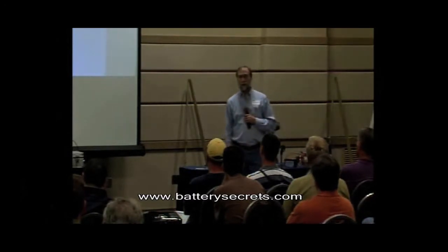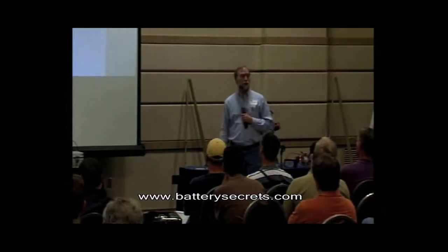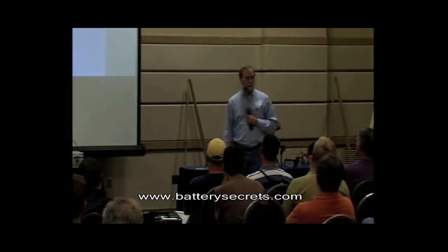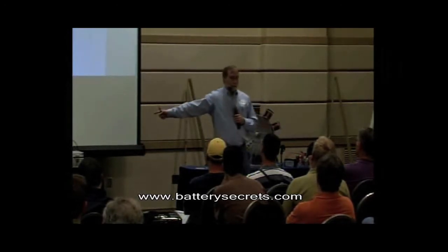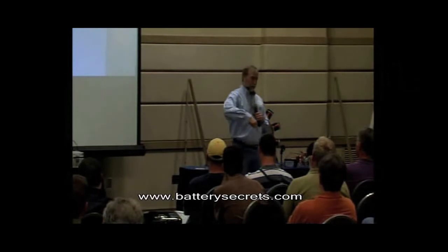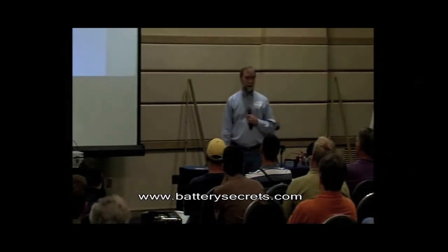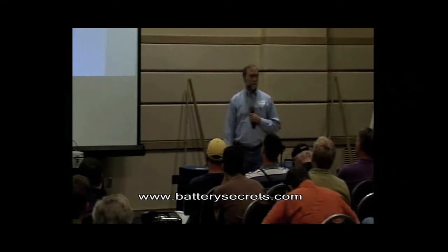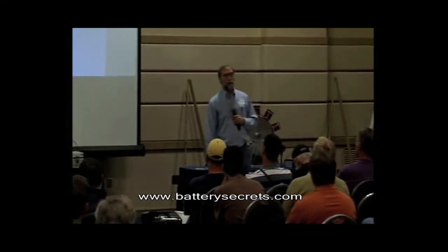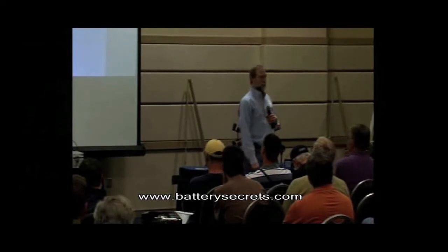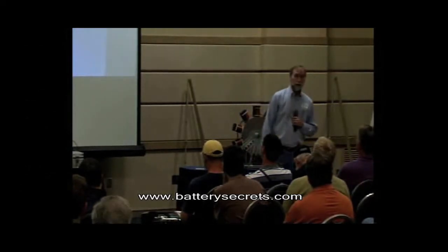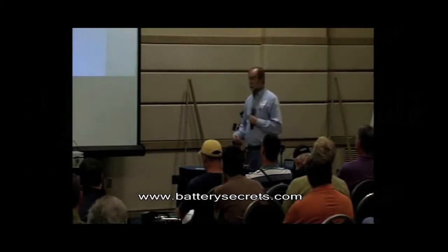You're lucky to get 30, 35, maybe 40% of that energy back. If you meter it from the wall with a standard charger, put it in the battery, and then meter it going back out, you're really lucky to get 35, 40% efficiency. It's atrocious. Because the battery's warming up during the charge. The faster you try and do it, the worse it gets.